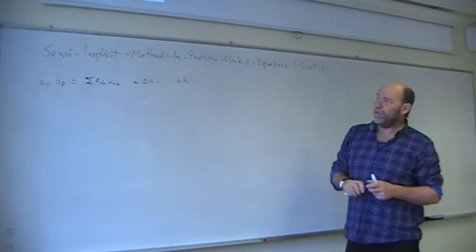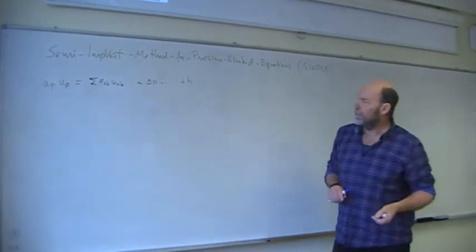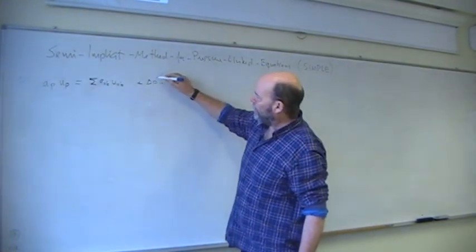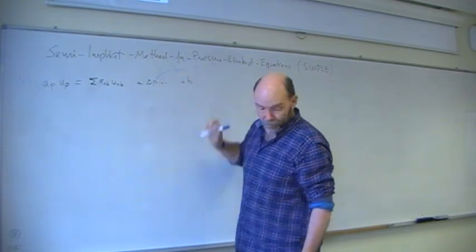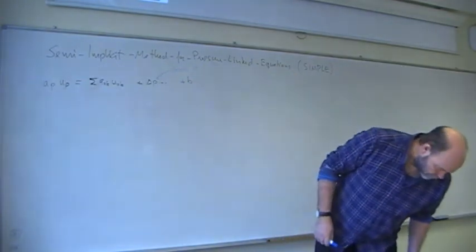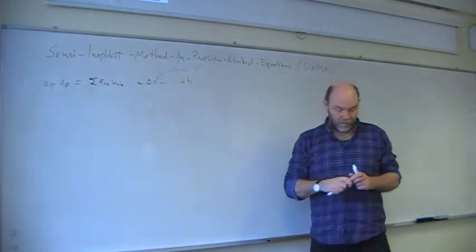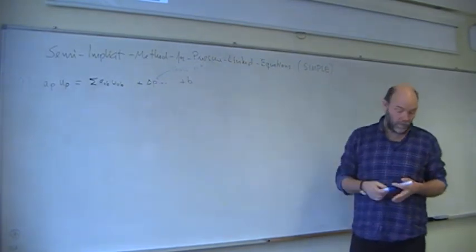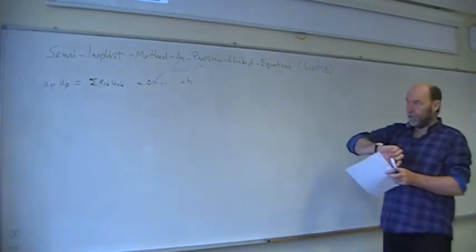Now we solve this equation by introducing something wrong. We don't know this pressure, it's also an unknown, so for this one we guess something wrong: pressure star. Then we can find a solution for u and the same with v of course, but it will in general be wrong.